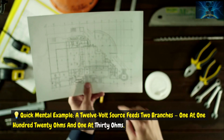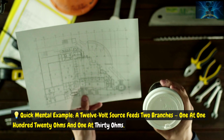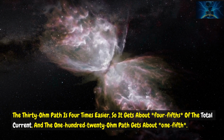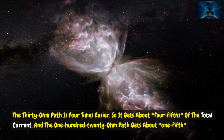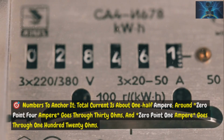Quick mental example. A 12-volt source feeds two branches, one at 120 ohms and one at 30 ohms. The 30-ohm path is 4 times easier, so it gets about 4/5 of the total current, and the 120-ohm path gets about 1/5. Numbers to anchor it: total current is about 1/2 ampere, around 0.4 ampere goes through 30 ohms, and 0.1 ampere goes through 120 ohms.